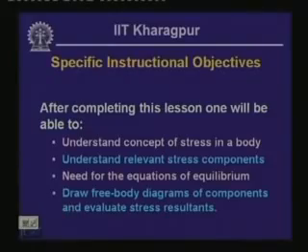In this lesson we are going through the aspects of stresses in such a way that once this lesson is completed, one should be able to understand the concept of stress in a body, understand relevant stress components, and understand why we need to go for the equations of equilibrium. For a given problem, one should be able to draw the free body diagram, evaluate the stress resultants from those diagrams and thereby compute the stresses.